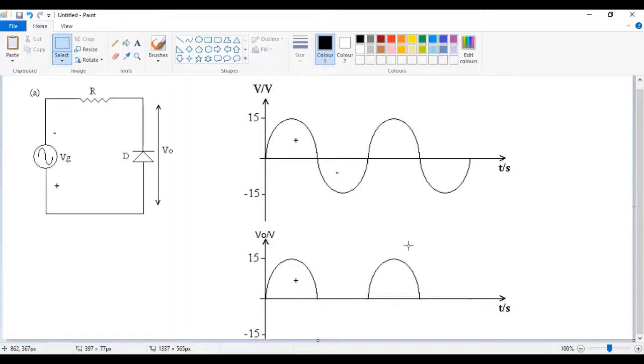So later down in your handout, you're going to find a section called half-wave rectification. It means we are maintaining only half of the cycles. We also have full-wave rectification. So if you use a diode bridge circuit, you can maintain all the half cycles, because each half cycle corresponds to energy. So this one is maintaining positive half cycles only and throwing away the negative half cycles. In a way, you're wasting energy. So this is one way you can look at it.